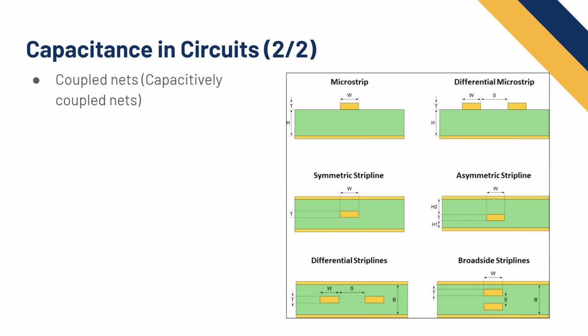As the high frequency communication starts switching up and down, it's going to have a low impedance to my power rail, and now my power rail has a bunch of switching on it, and that's not very good, right? That might affect everything that's on that power rail. So it's just something to keep in mind when you're routing high speed. It should be far from your power, and your low speed should be far from all the high speed.